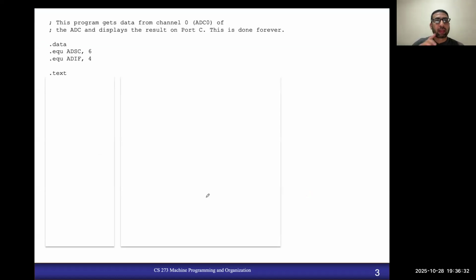No? Okay. So here actually I am not going to write the code. The code is already in the slides, but I want you to write the code, or at least give it a try, right? So the first thing is you need to configure both port B and D as output ports, because I want to connect LEDs on these ports. So I'm releasing this poll. You can go ahead and try to do this question.